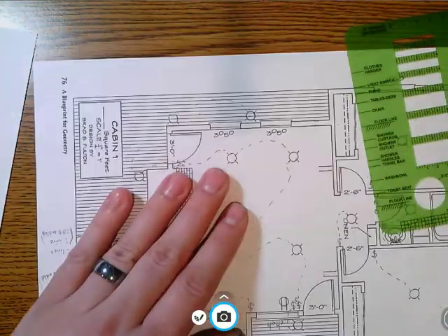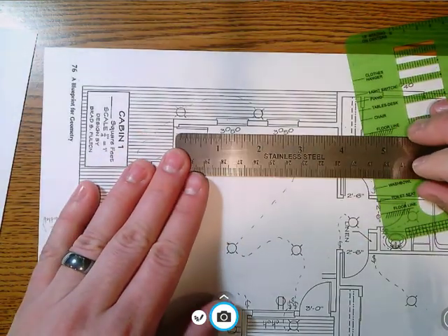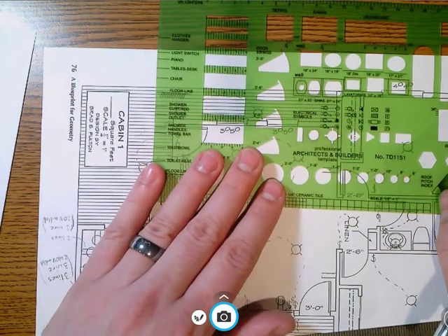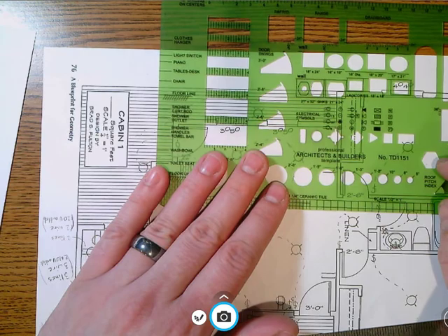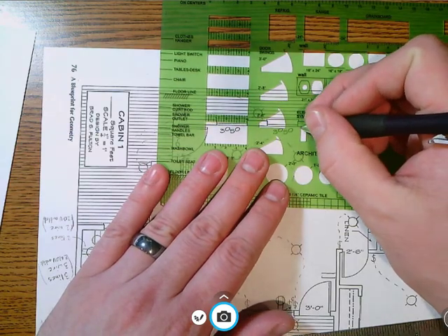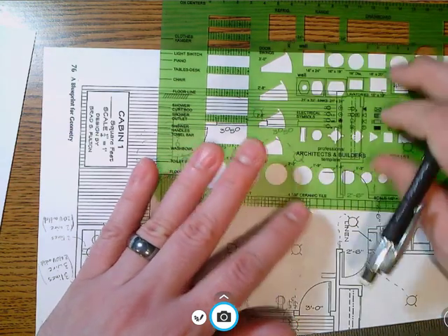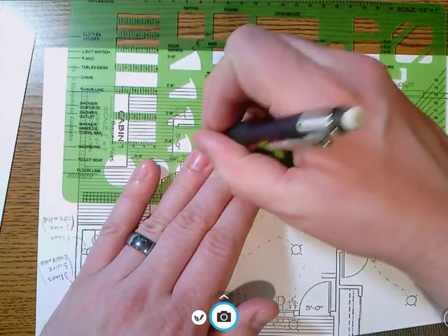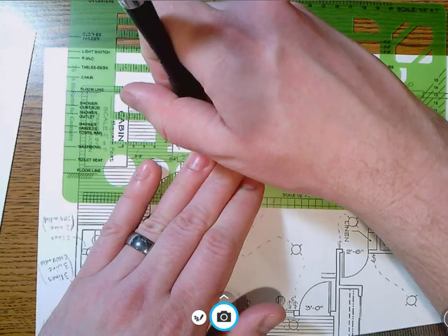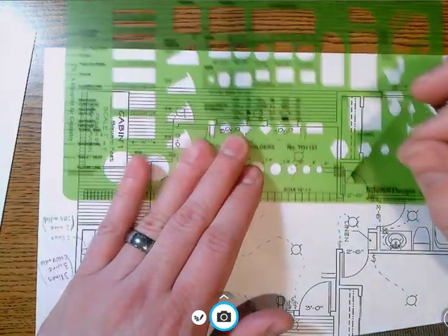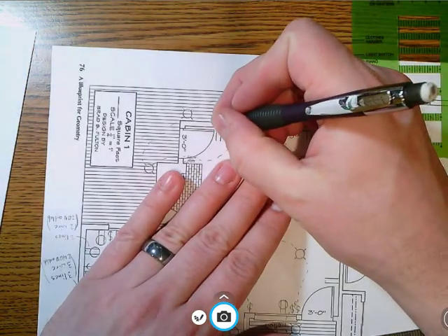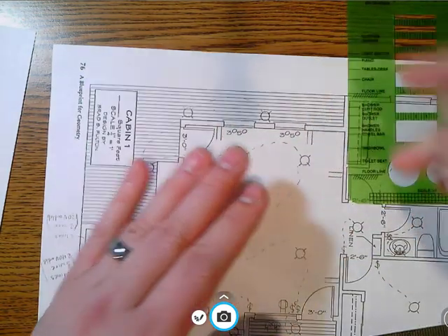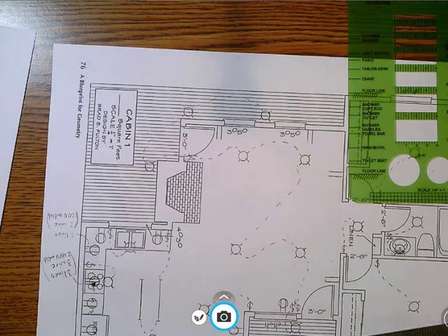And now, how long is this segment? This again is over 12 feet, so I really have to do 2 outlets here. And having a few extra outlets is fine. What I really want to avoid, and I've seen students do this in the past, is they worry that they're going to fail the electrical outlet requirement because they don't understand the 12-foot component.